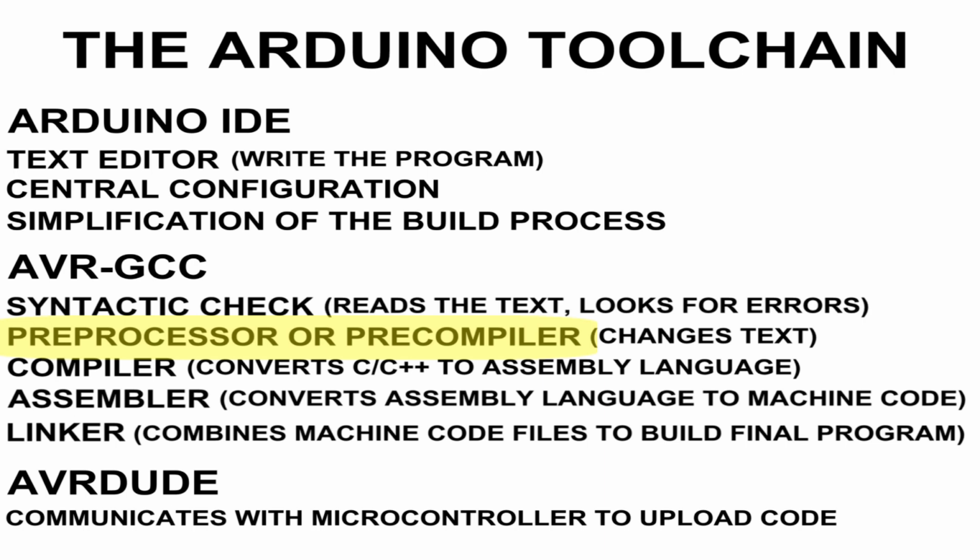Once the precompiler finishes, the completed text is loaded by the actual compiler, which creates an assembly language file. The compiler automatically includes all the machine instructions specific to the processor being compiled for. Now the assembly file is handed to the assembler, which builds machine code. The machine code is then passed to the linker, where any pre-assembled binary includes are linked with it. At this point, the file is a completed executable, and the uploader sends it to the board.